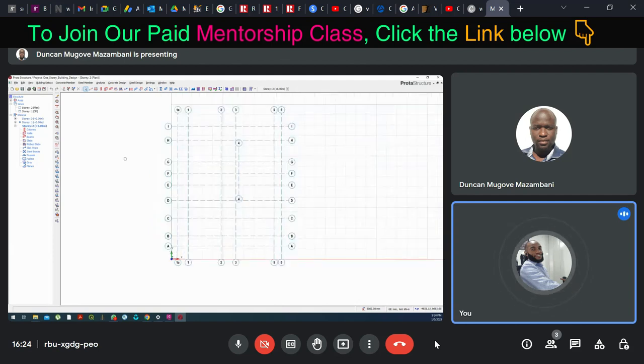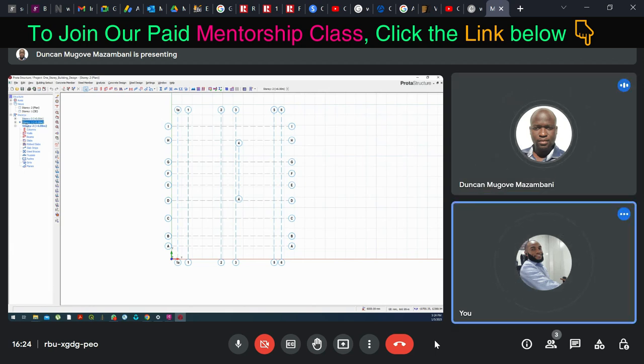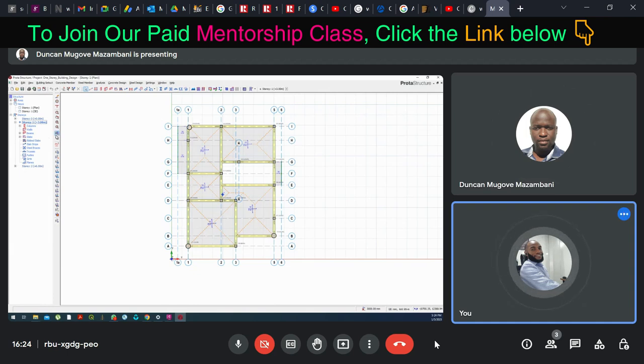So click back on story one, make story one active now. No, story one, that's story zero, that's foundation. Story one, double click on story one. Okay, that's fine. Now go back to Building Setout at the top there, and then click on Generate Story. So we are trying to now copy the columns and the beams onto story two. So click there.